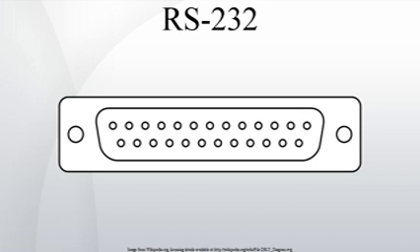This scheme is also employed on present-day RS-232 to RS-485 converters, where the RS-232's RTS signal is used to ask the converter to take control of the RS-485 bus, a concept that does not otherwise exist in RS-232. There is no way for the DTE to indicate that it is unable to accept data from the DCE. A non-standard symmetric alternative, commonly called RTS-CTS handshaking, was developed by various equipment manufacturers.